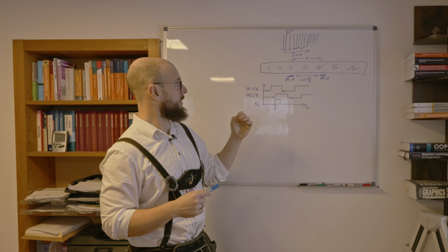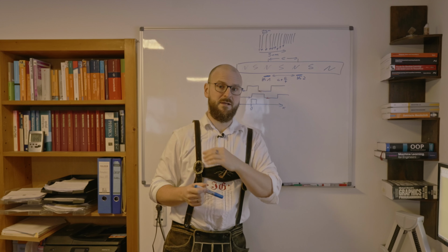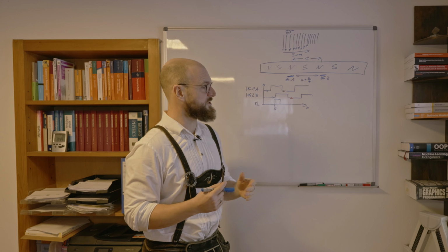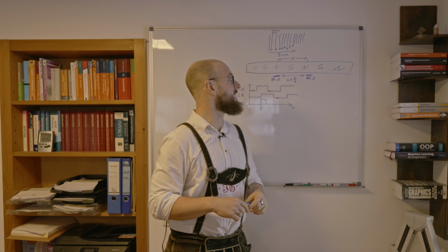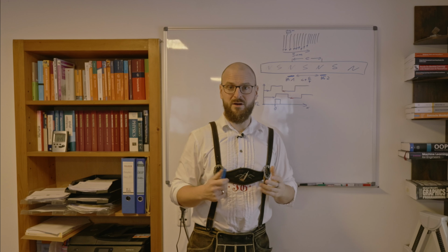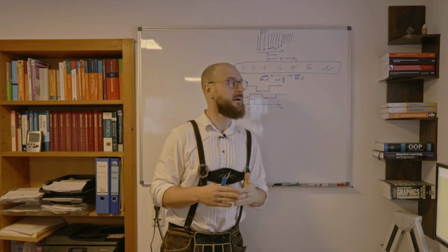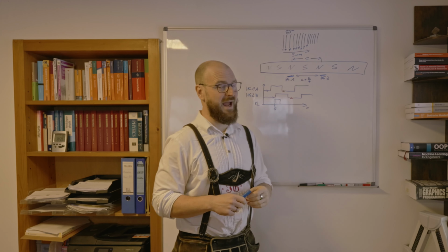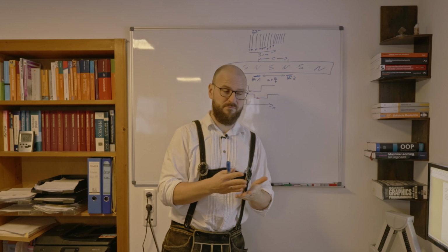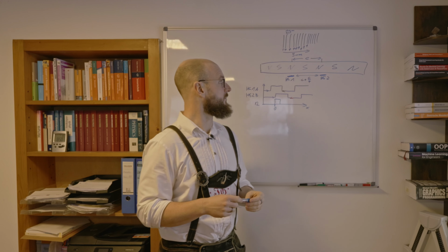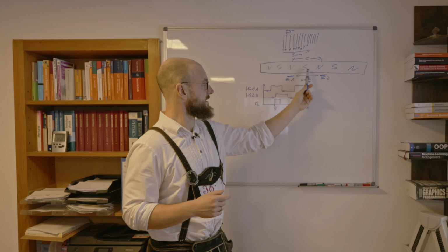For coping with that problem, on the one hand, we could use optical systems. With optical systems, it is much more feasible to build smaller lines, and by that increase the resolution and accuracy of the optical incremental encoder, just by increasing the accuracy of the lining on the tape. That's one possibility, but that possibility also has some limits downwards. Another idea would be to use the behavior of the sensors itself.